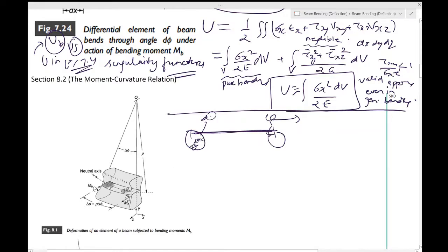We have seen that mechanism, I think, somewhere in chapter 6 or 7, I'm not sure where, in chapter 6 in torsion. Now if this particular shaft, which experiences both torsion and bending according to your figure 6.1, becomes deflected like this, despite it not actually failing stress-wise, this is still bad, because you cannot allow your shaft to be like this. It will start touching parts of the machine which it should not normally be in contact with, then it will wear, and the machine will not be usable anymore. So it is not just the stresses which we must consider, but also the deflections.